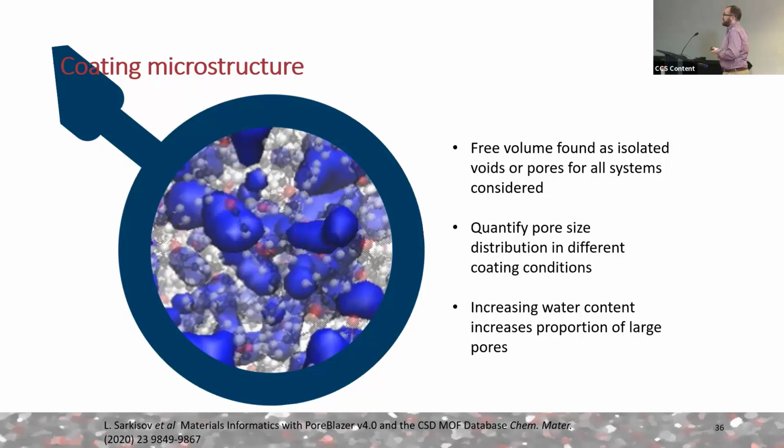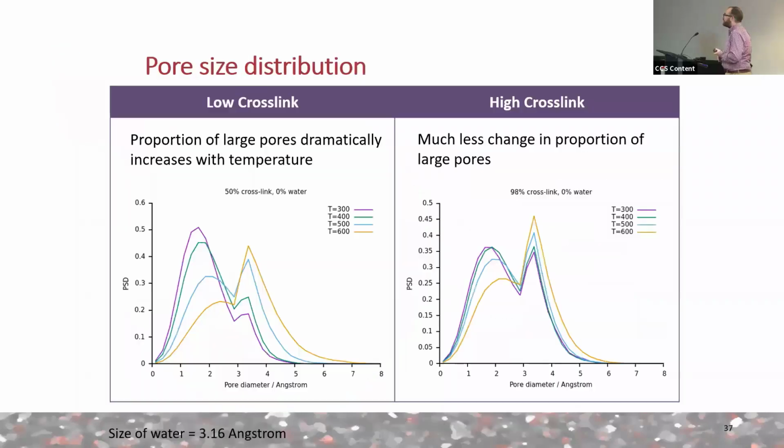The nice thing about simulations is I can then quantify the pore size distribution at these different conditions. So the final thing that I'm going to say on this slide is increasing the water concentration increases the proportion of large pores, which is to be expected because there's more water there, so your coating swells slightly. But all the trends that I'm going to tell you about in a minute were the same for all water composition, all the water content.